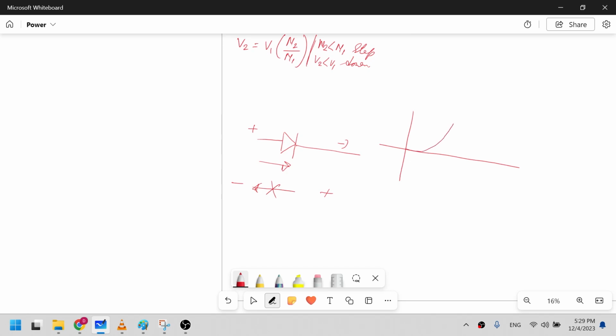So if you give a positive voltage, the positive bias, meaning this direction, after a certain voltage, this voltage is typically between 0.3 to 0.7, the current flow, the amps, increases rapidly. This is the V. So the current flow increases rapidly, so it behaves like a no resistance path.